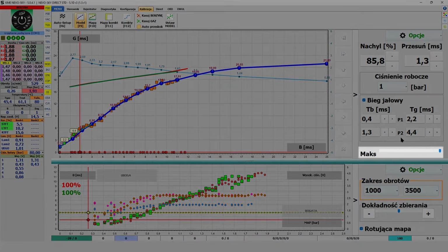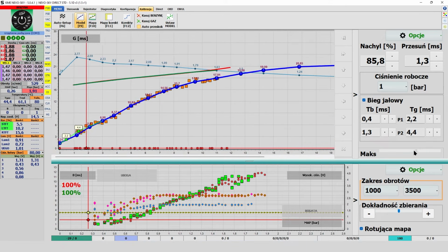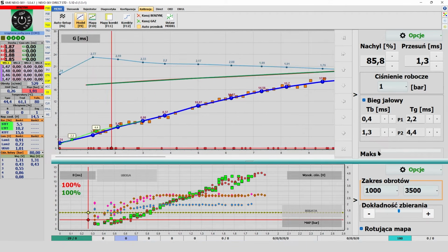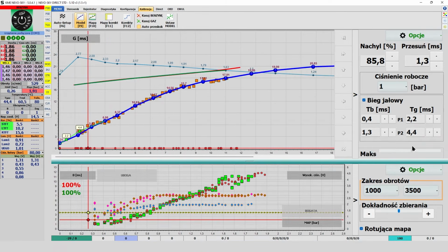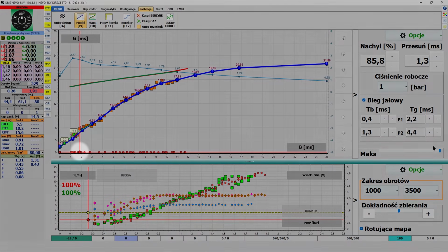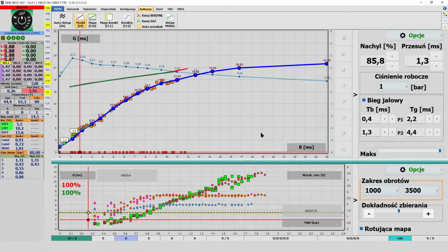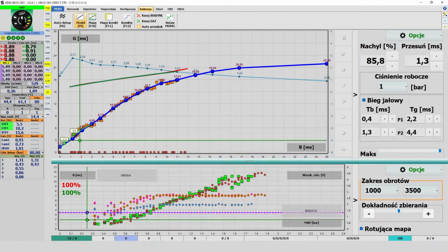Max. With the help of this slider, it is possible to change the scale of the timeline of the gasoline model. This makes it easier to position the model when there are several points next to each other in the chart. The model graph shows the instantaneous point of the system, illustrated by a rhombus-shaped point. When the system is running on gasoline, the color of the rhombus is red, and when working on gas, green. In addition, 2 types of points are shown.